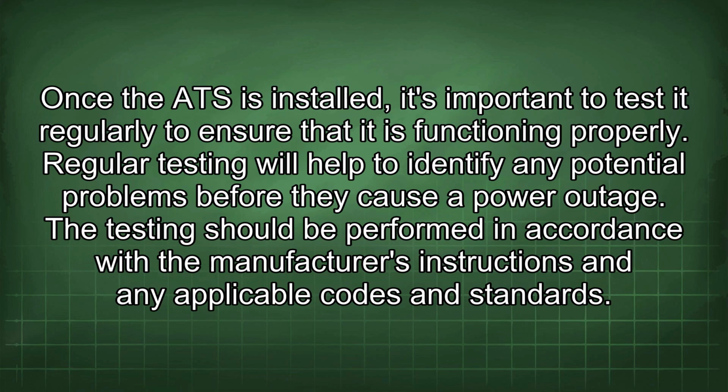Once the ATS is installed, it's important to test it regularly to ensure that it is functioning properly. Regular testing will help to identify any potential problems before they cause a power outage. Testing should be performed in accordance with the manufacturer's instructions and any applicable codes and standards.